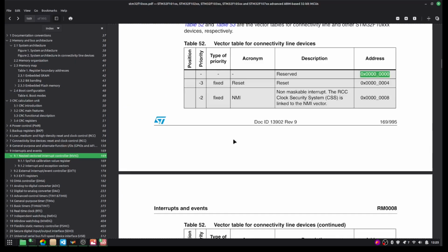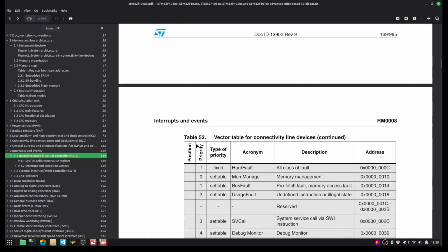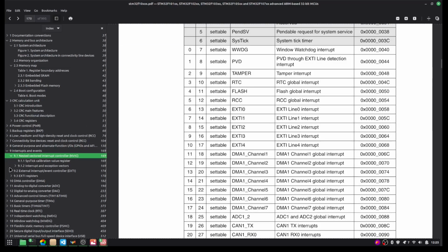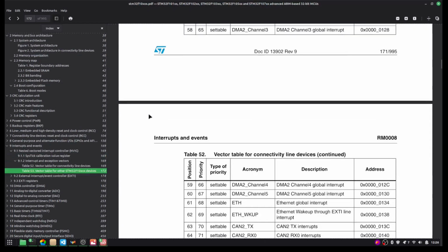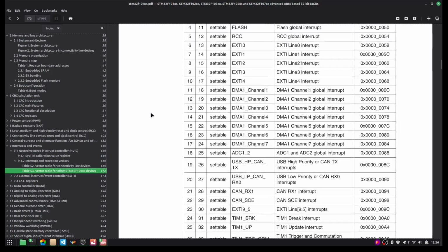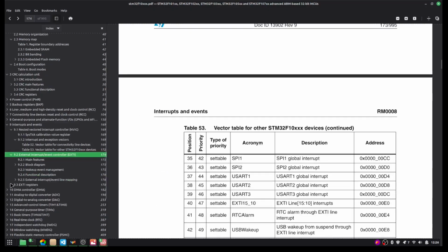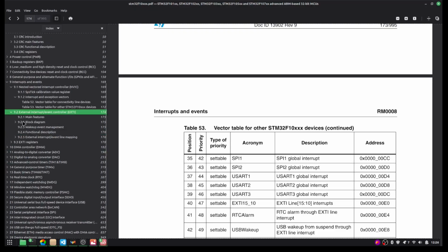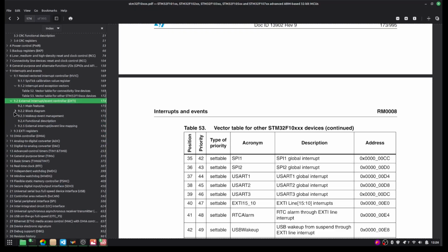It's very important. Otherwise, if you have interrupts within the application, it will jump into the flash address where the boot is present. You don't want that. When you have three vector tables, the application must use the vector table assigned to it. Clear? Now, the way this is done is using the vector table offset register. Now, where it is, we will see. Might be part of the system registers, but we will see it.